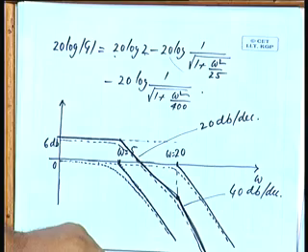Now, instead of increasing the frequency tenfold in an expression like log of omega, if I increase the frequency tenfold, then I get an additional term of 20 log of 10, is it not, plus 20 log of omega. If I increase the frequency twofold, that is if I just double the frequency, then what will be the additional term? 20 log of 2. I have just doubled the frequency. So, 20 log of 2 will be the additional term. How much is that? 6 dB. So, 20 dB per decade is same as 6 dB per octave. This octave is different from the octave that we use in music systems, in sound. Octave here in electrical engineering, when we talk about frequency response, octave means double the frequency, that is the second harmonic. So, for any omega, if I double the frequency, there will be an increment or decrement of 6 dB. So, sometimes these slopes are written in many books, you will find 6 dB per octave. It is as good as 20 dB per decade.